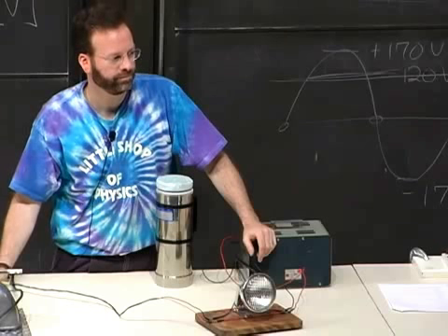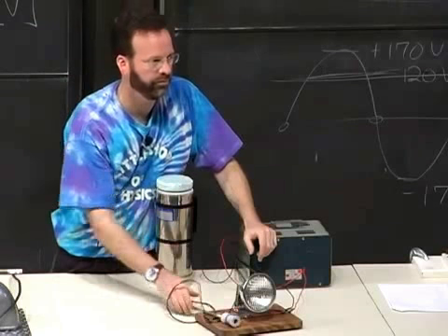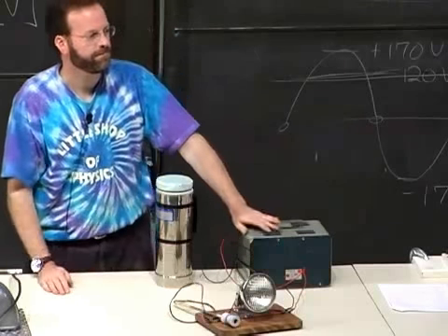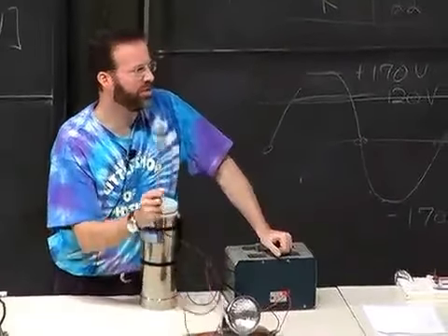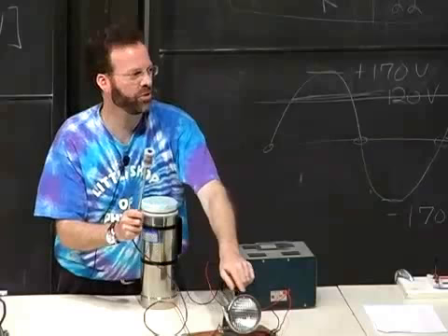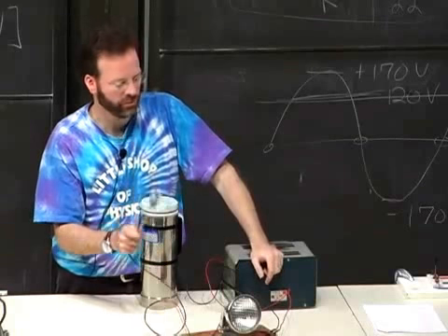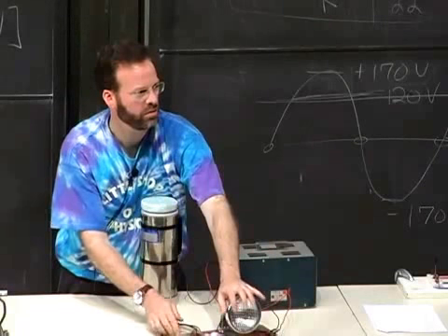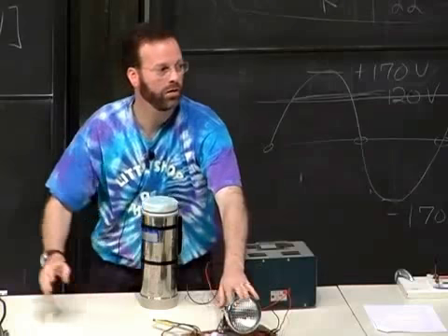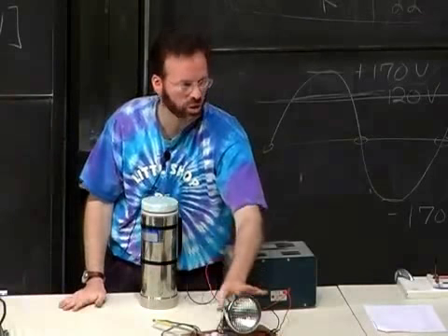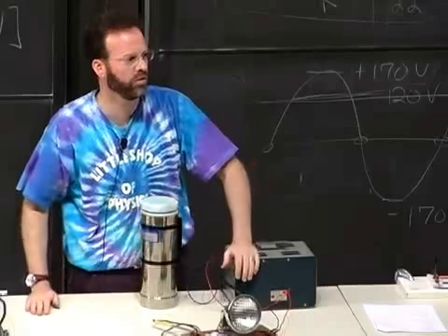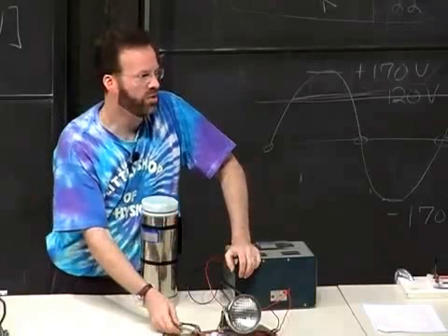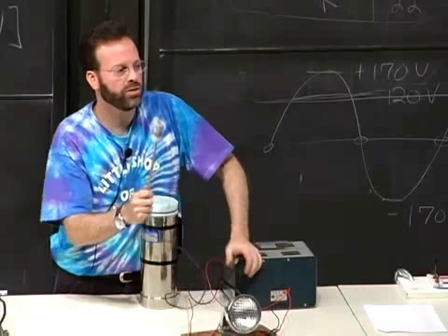So it's the resistor that maintains it at a level that we can use, yeah. Remember your question before, Ennis? We can use this to regulate how much current flows through. If we know the resistance of this, we know its power, we know how much voltage and how much current it needs, and we can hook it up directly. We can control that and make it perfect. This one wasn't, so yeah, we put this in series with it to regulate it.